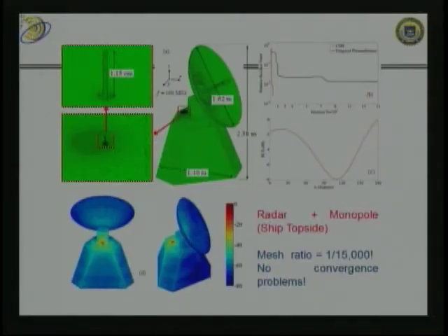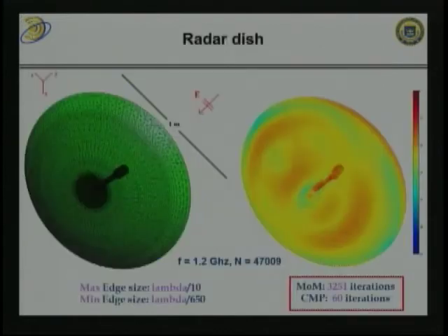Without preconditioner, look at the upper graph there. The residual error in the solver, as a function of iteration count, just does not converge. But with the Calderon preconditioner in place, it just takes 20 or 30 iterations for this thing to converge. The same in time domain. Just more of the same.